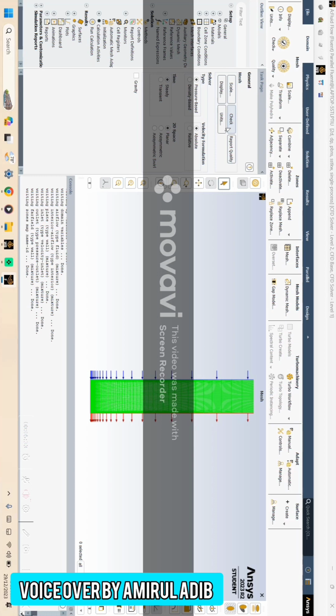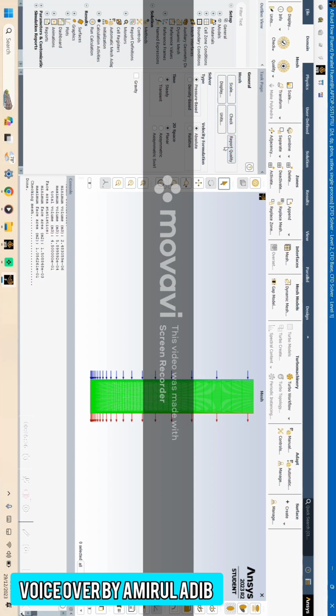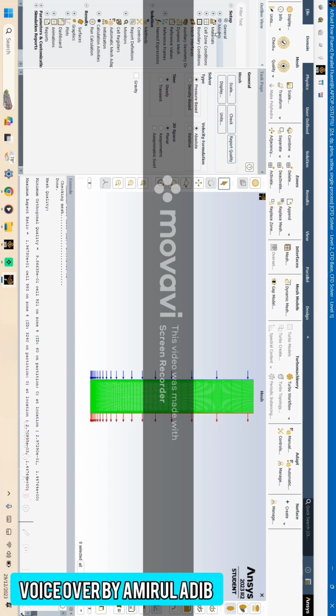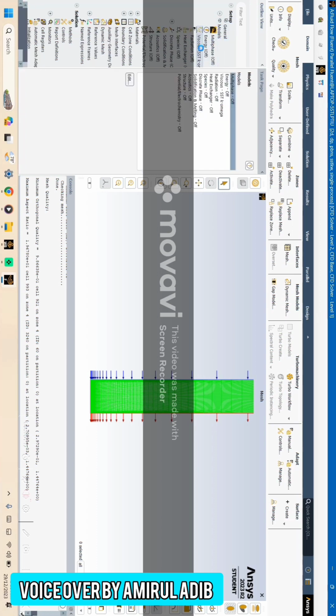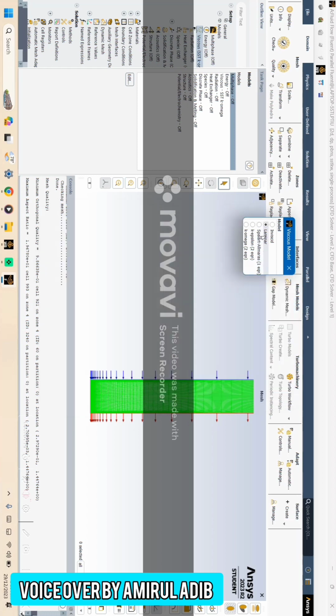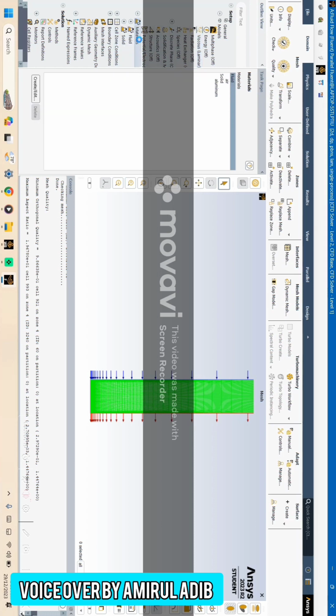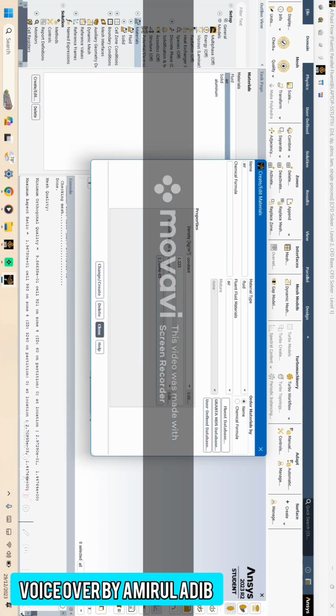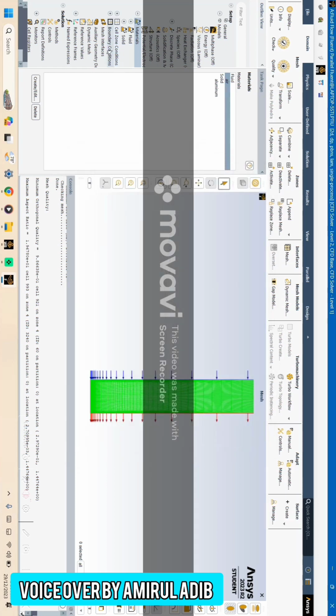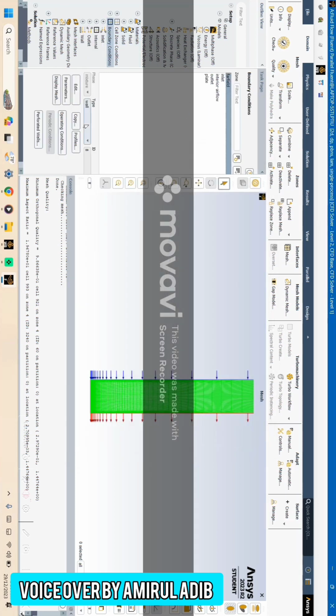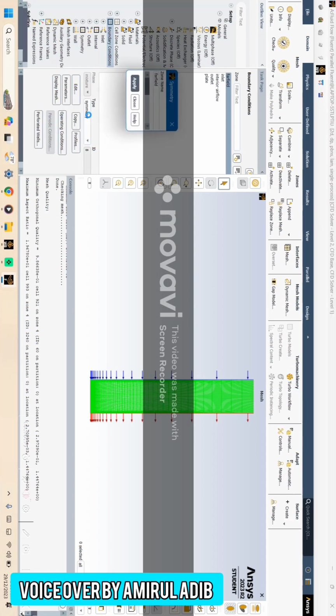After the loading has completed, firstly we click check and report quality, and then go to the model, viscous, choose laminar, click OK. Okay, and then go to materials, click air, we open it and change the density and viscosity to 0.001. Click change, close. And then go to boundary conditions. For the far field, we choose symmetry,